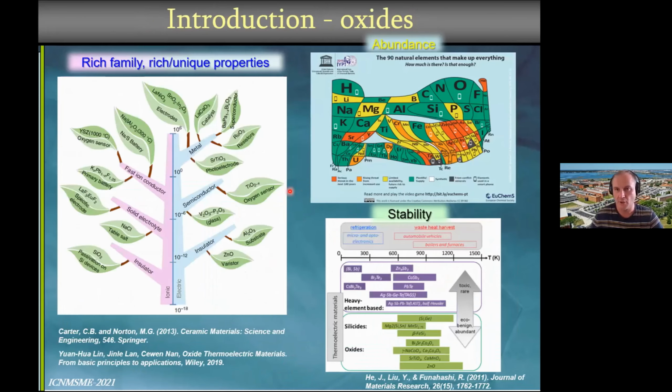And regarding oxides, of course, you know that microstructure is decisive in defining their potential applications. Oxides are already known as thermoelectric materials as well. In general, ceramics show probably the broadest range of electrical conductivity compared to any other type of material. So it covers a range of over 24 orders of magnitude.